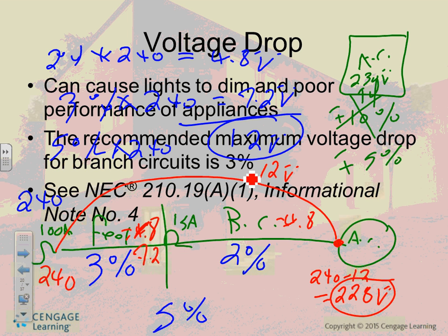Now, what happens if your voltage here is 220? It dropped too much. And then what they do with the equipment, guys, they make the equipment rated for 230 here. Even the manufacturers rate their equipment for an even lower voltage, 230. So you are now within the range of, remember, 230 plus or minus 10 based on the manufacturer. You dropped a little bit lower than 230, you're within the range of this equipment. So you still function. Go lower than that, the equipment is not guaranteed to start.